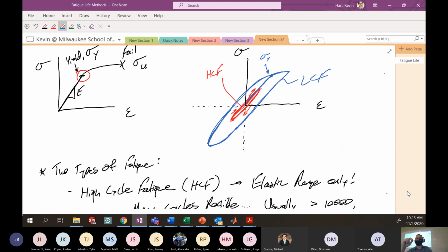But as soon as I start getting more aggressive with it, start pulling it beyond what would be a yielding condition for the plastic, you'll start to see some whitening in this hinge area here, and it becomes very easy to break it after only 5, 10, 15 cycles. This is low cycle fatigue, a low amount of cycles required to fail it because you're introducing this plasticity. So if I get more aggressive with it, I could eventually break it off if I wasn't super weak. Okay, there you go.